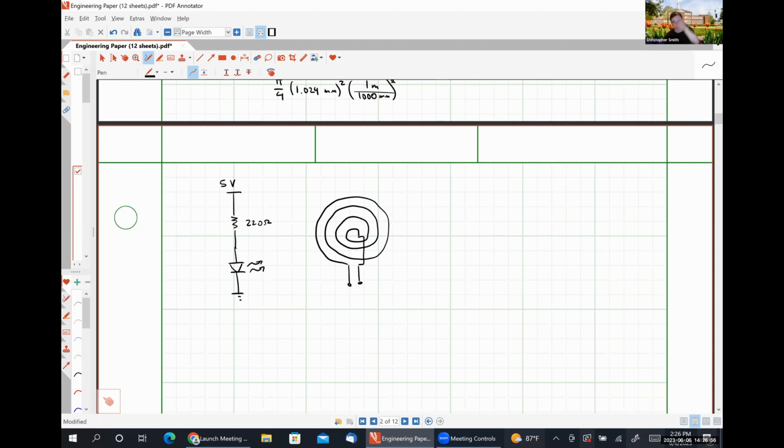And so whenever you put it in a coil like this, the current has to travel further in a material with a high, I forget the name of it already. The resistivity. Resistivity has a high resistivity, but then when you pass a lot of current through it, it has a long way to travel, and so then it heats up as a result.